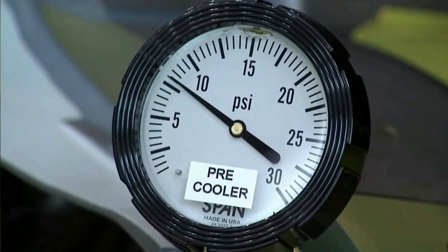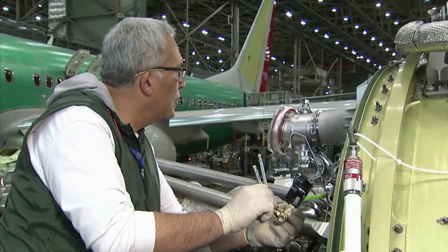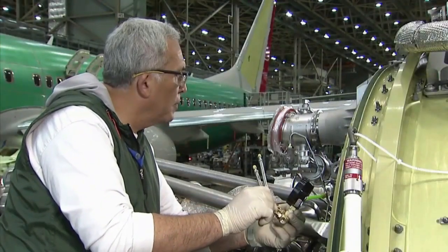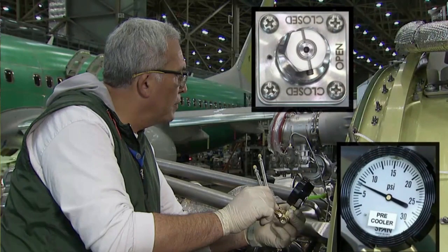With good control pressure, you can use the needle valve on the test assembly to simulate the venting action of the 390 sensor while you observe the control pressure. Also observe the PCCB to see if it opens per the aircraft maintenance manual.